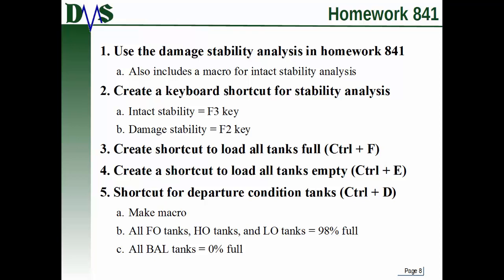And then finally, I'd like you to create a special macro for departure condition on the tanks, and that'll be assigned to the Control D key. What I would like you to have this do is you're going to make the macro where all fuel oil tanks, all HO tanks, and all LO tanks are all 98% full. And then all ballast tanks, BAL, any tank that starts with BAL, is 0% full.